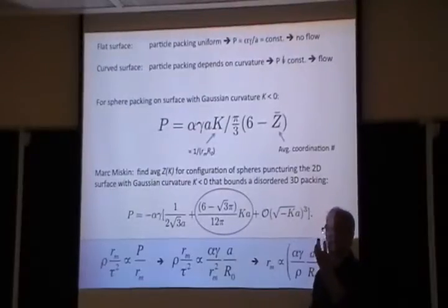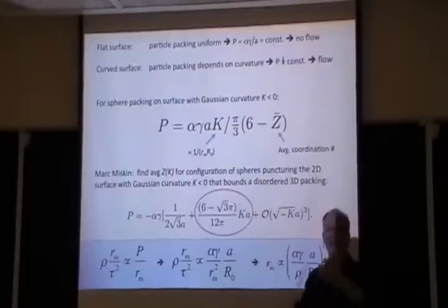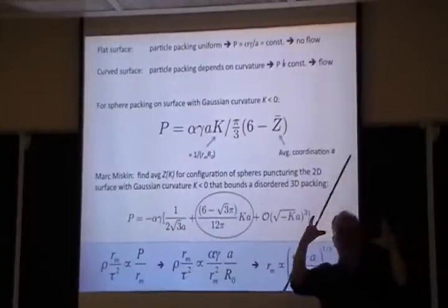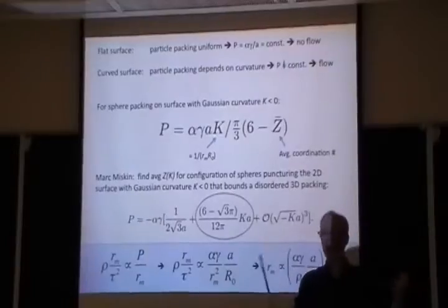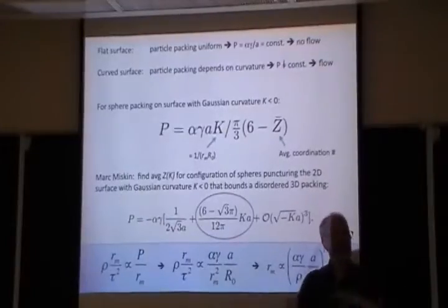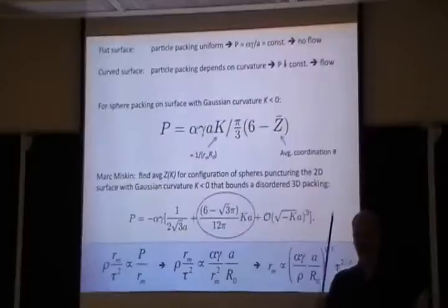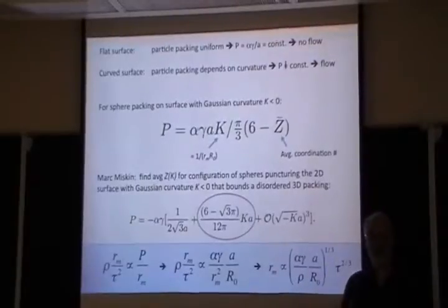Right, that's for one of these interfaces, one of these menisci. And say, well, how many menisci do I have over some typical area? And they would all push in. So you can count menisci, but that depends on the particle packing. The more particles you have, the more menisci you have, and also the tighter they are, right?